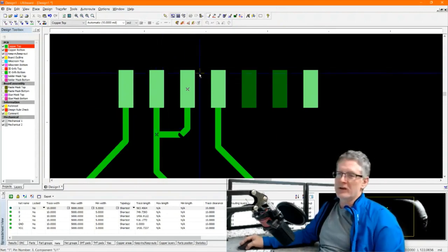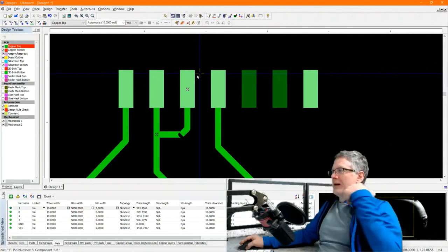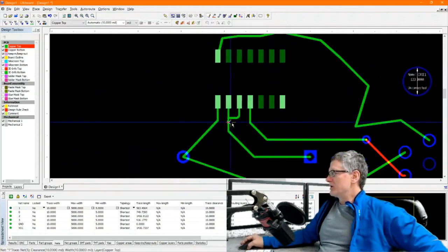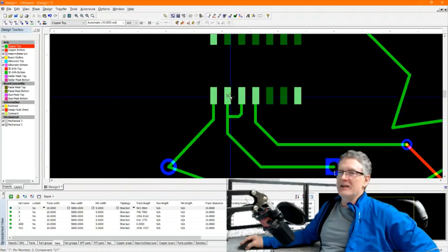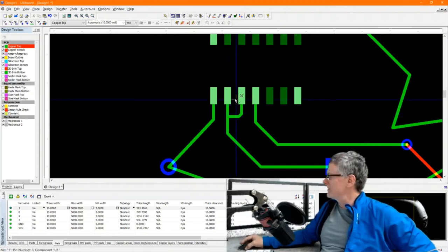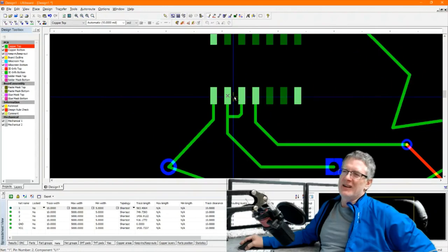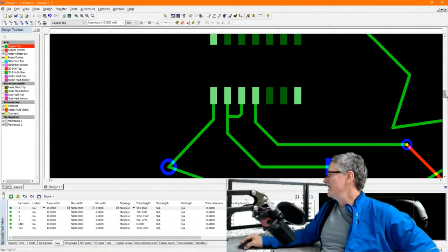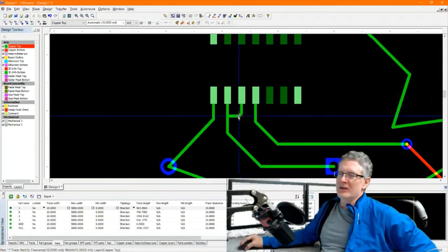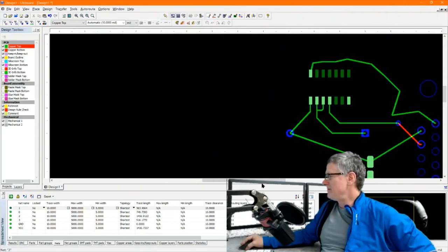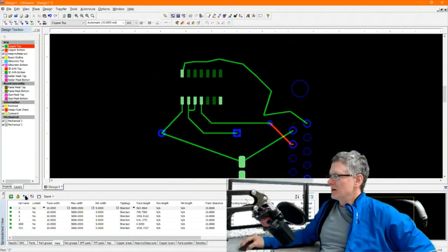If I can avoid going underneath, then if I'm trying to troubleshoot this board, I can visually see that there's a connection there, and I don't end up cutting that trace out. I actually did this once where I'm going, is there something in there? And I cut it out, and then I had to bring up the schematic and realize no, those 2 points really were connected. If the guy doing the layout had just done this, I'd have known that right away. So there you go.